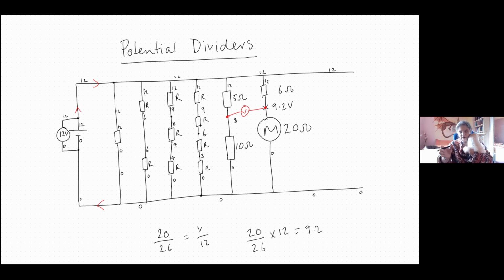It doesn't happen. And that's because the full 235 volts or whatever it is is across every single component that you plug into the mains. Every single one gets the full potential difference because everything in your house is connected in parallel. Even in cars, every headlight, every windscreen wiper, every window winder, every mirror adjustment motor, everything is connected in parallel. And so none of them affect each other.